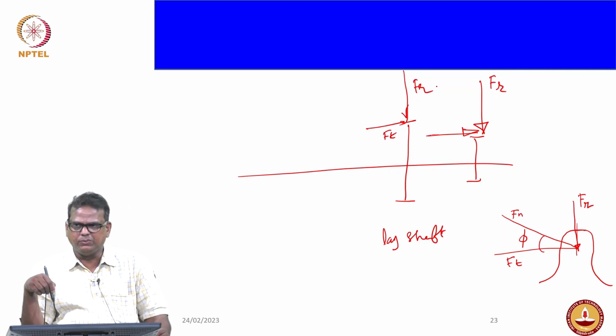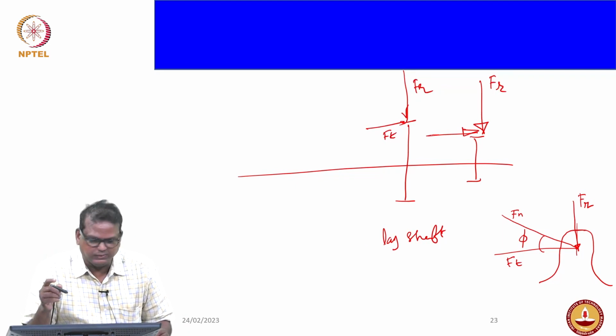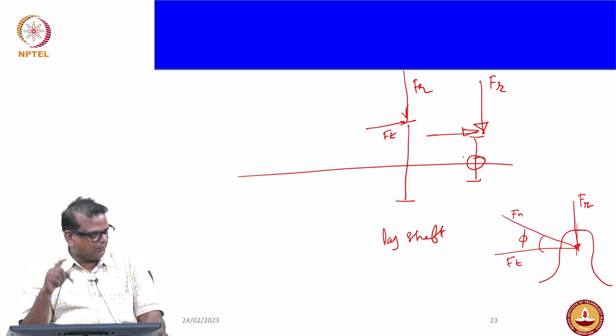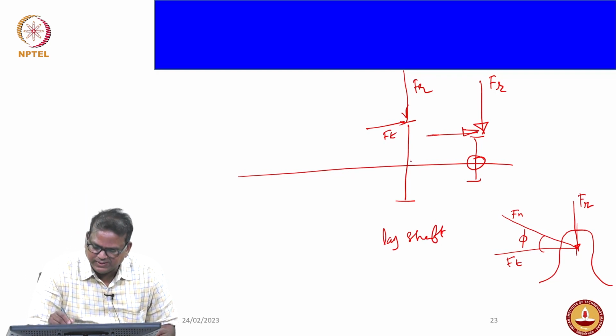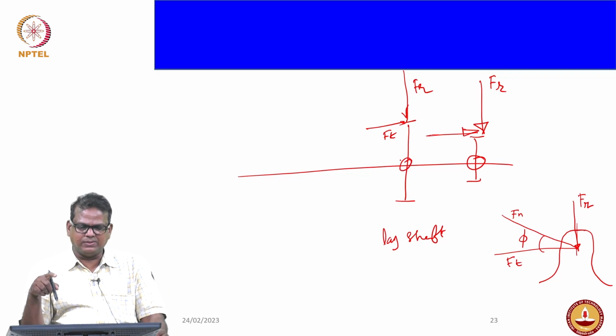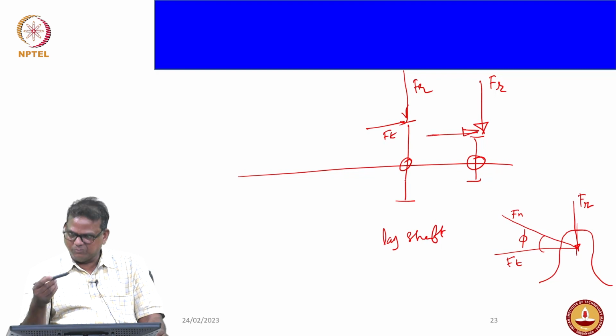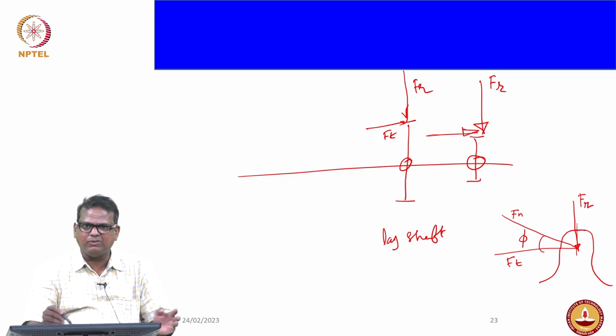So whenever you do the calculation, you take a particular gear, apply the load, try to find out the diameter, and move on to the next. Because torque is constant, but Ft will change; Ft and Fr keep changing. Again for that particular gear position, you have to find the moment, then from the moment find the diameter. So this is the way you approach it.